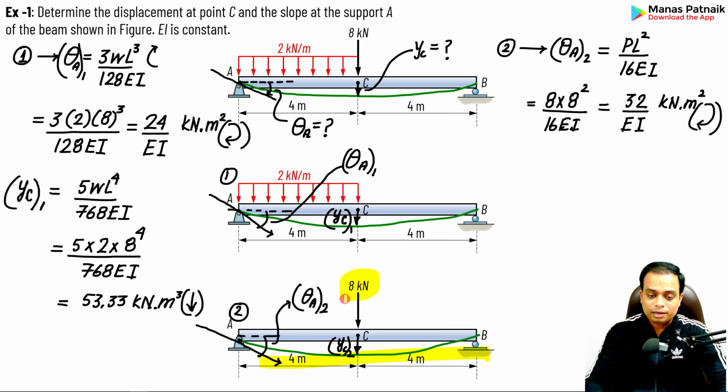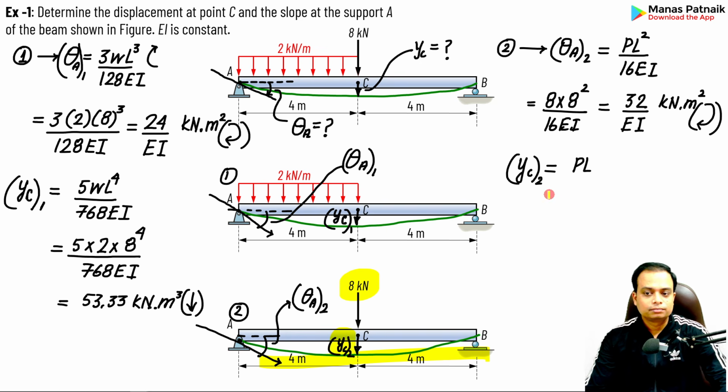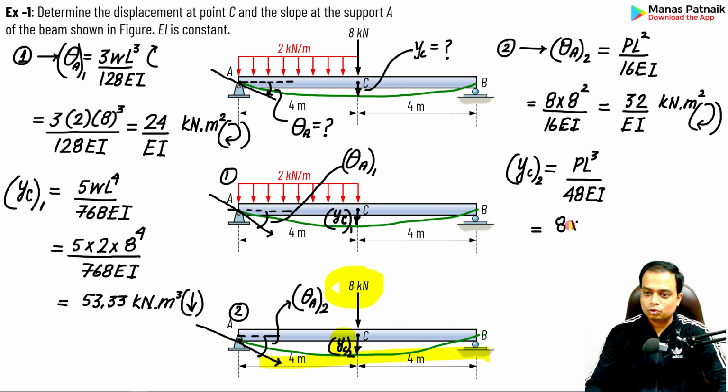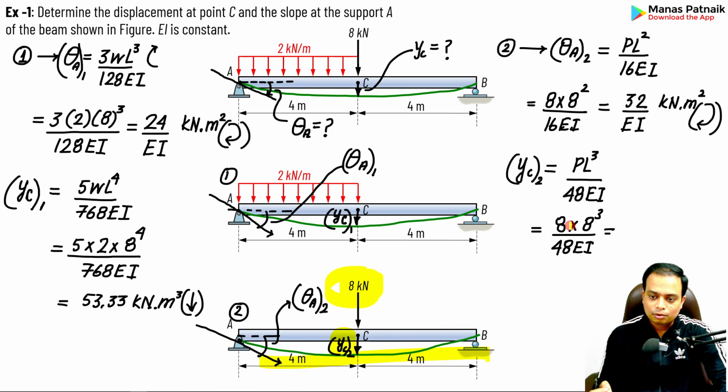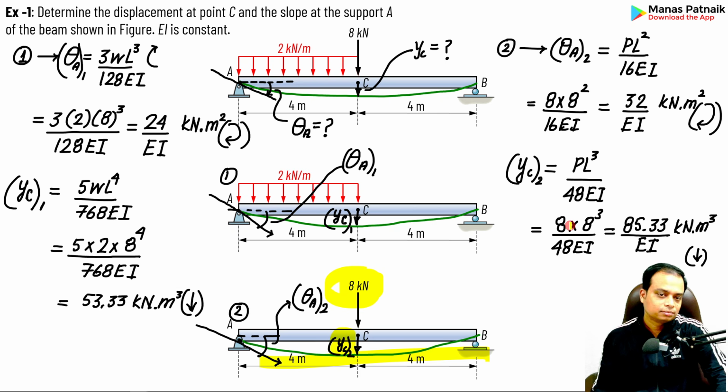on a simply supported beam with just a point load acting centrally, okay, on one end. Next, we are going to calculate this deflection. Here we go. That's the formula if you recall. Now you need to plug in the values. P is 8, okay. L is 8 again, 4 plus 4. So when you plug in all of these values, what you get is an expression like this.